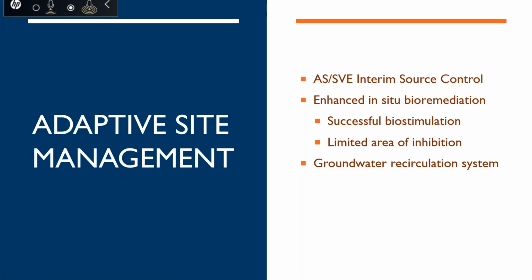You know, the air-sparge soil vapor extraction system that they had was an interim control measure for mass discharge from the source zone. It removed more than 20 tons of chlorinated hydrocarbons from the subsurface for a 7-year period. However, a later passive flux meter survey provided evidence that the system bisected the original NAPL and that the mass discharge was passing underneath that air sparge curtain. Therefore, additional measures were going to be needed to decrease the concentrations.